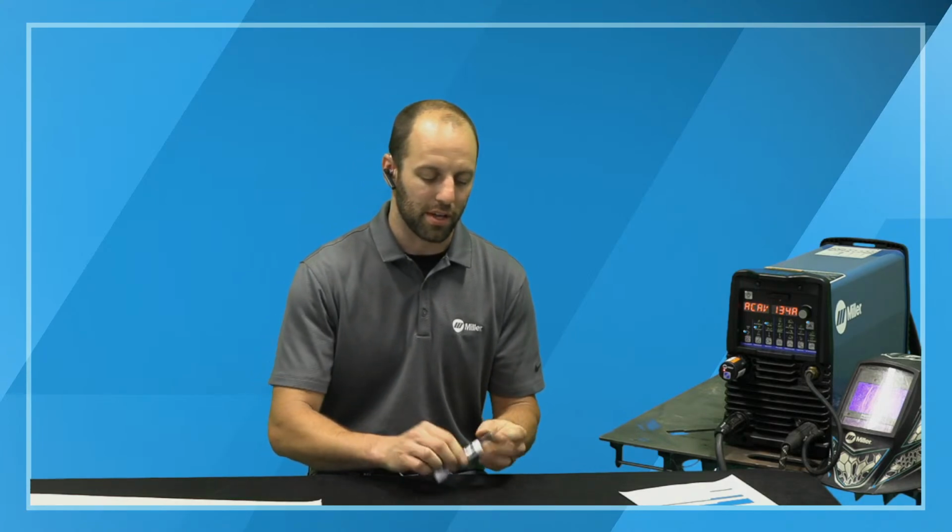There are certain applications where DC welding of aluminum can and should be done, but it does come at a disadvantage. If we look at the different polarities that we talked about earlier, electrode negative is generating a lot of heat into the workpiece. 70% of that heat is going down into the workpiece. Electrode positive, really the only reason why we do that is to get that oxide removal. That's the primary purpose of it and why we do it.